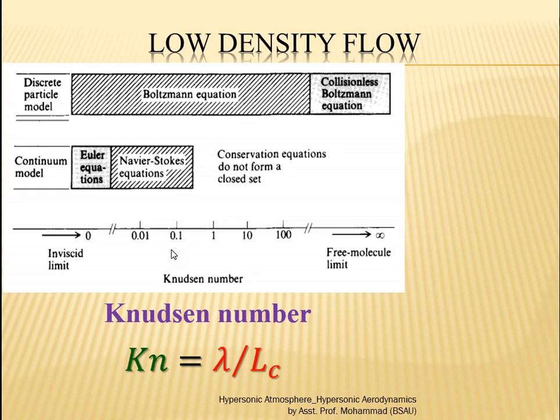Here also, even if the continuum Navier-Stokes equations are applicable, the slip conditions have to be injected and put there to do the correct analysis, and that becomes important for the Knudsen number as low as 0.03. Even the figures are similar. So for large values of Knudsen number, slip conditions start taking place, and this must be accounted for in any regime for Knudsen number more than 0.03.